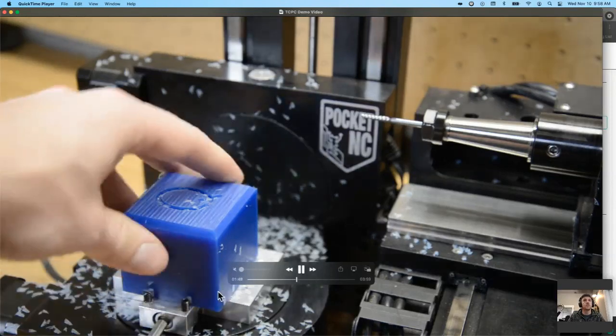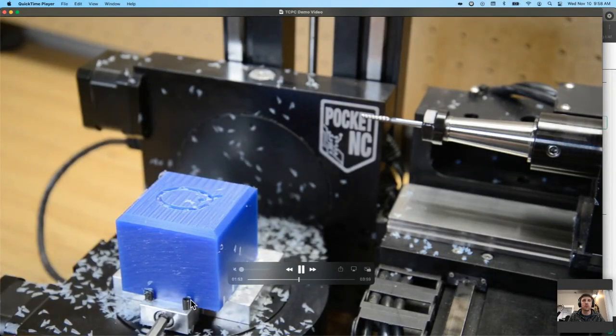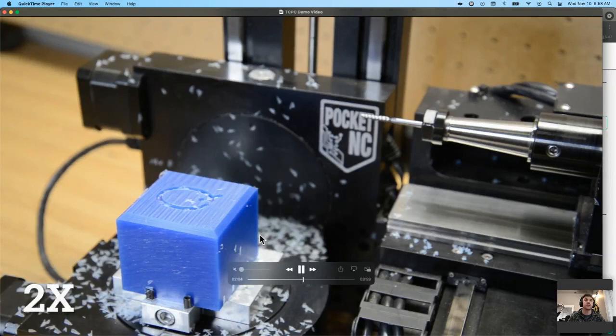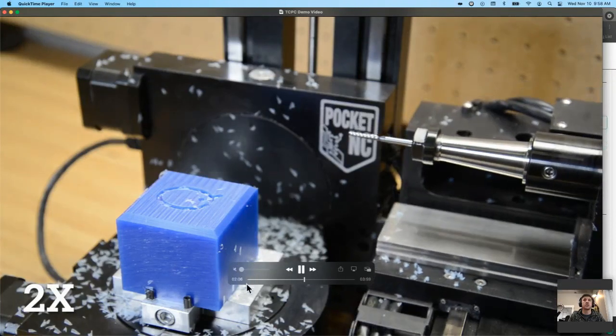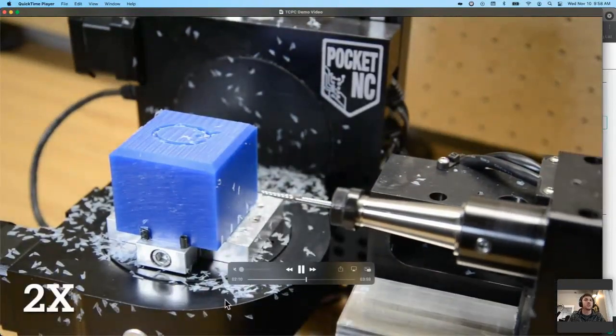It didn't technically move in Y, or didn't move much in Y. You can see I'm realigning it just with little dents here. Not the most accurate, but for representation purposes, we can say that Z didn't move. Y obviously didn't move because we're referencing the bottom of the block, but X moved about 0.2 inches in the positive direction.